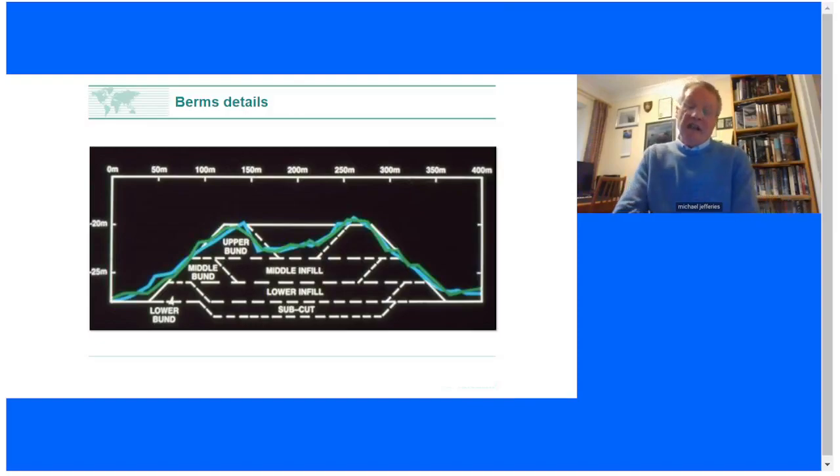Now, nobody's ever seen a berm. They're underwater, so they'll never be seen by human eyes. So everything is done using remote sensing and echo sounders and such like. So we're building this using remote tools. And what you're looking at here is a photograph taken of the computer screen plotting up our survey data. A design drawing for the berm we're trying to build, and the blue and green lines are a couple of survey transects which we're checking out how well we're doing.